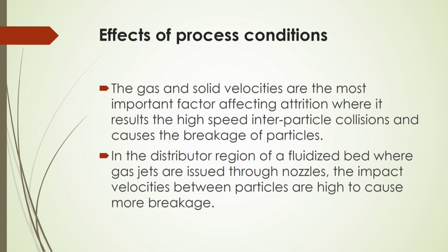And generally it is seen that in the distributor region, high kinetic energy will be there in the fluidized bed, where gas jets are issued through the nozzle, and the impact of the velocities between the particles is high enough to cause more breakage there. So, that is why the gas velocity or solid velocity plays a predominant role in the attrition of solid particles into finer ones.